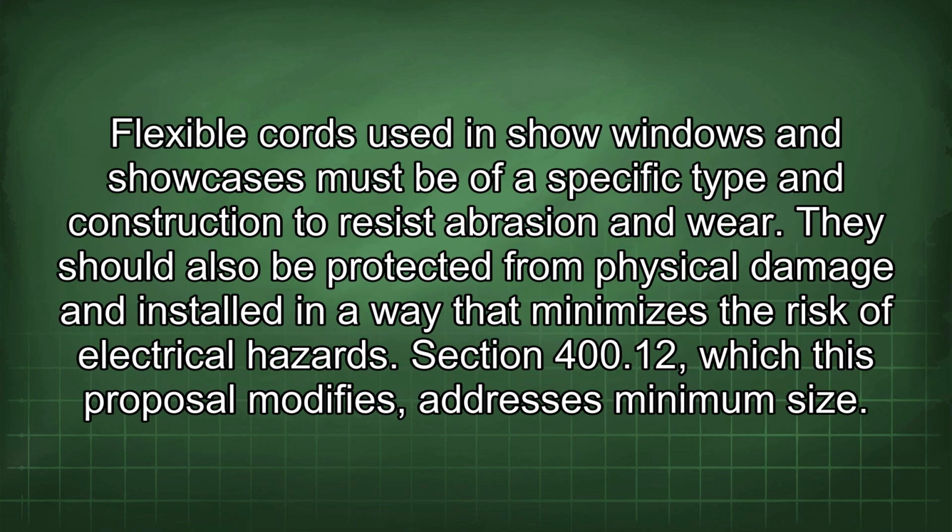Flexible cords used in show windows and showcases must be of a specific type and construction to resist abrasion and wear. They should also be protected from physical damage and installed in a way that minimizes the risk of electrical hazards. Section 400.12, which this proposal modifies, addresses minimum size.